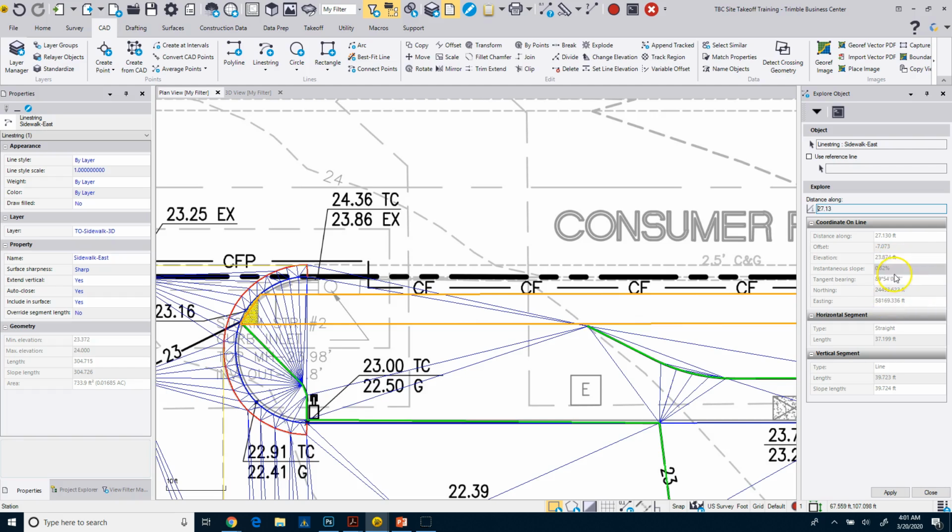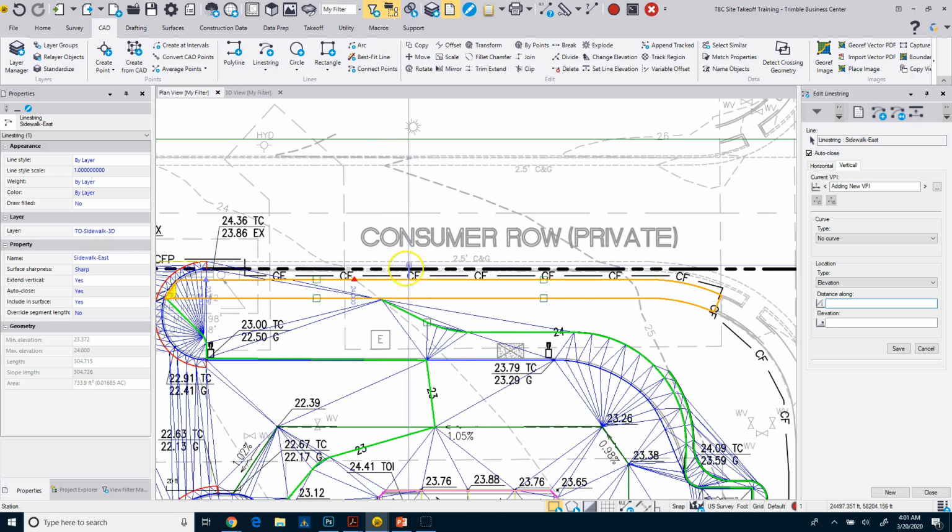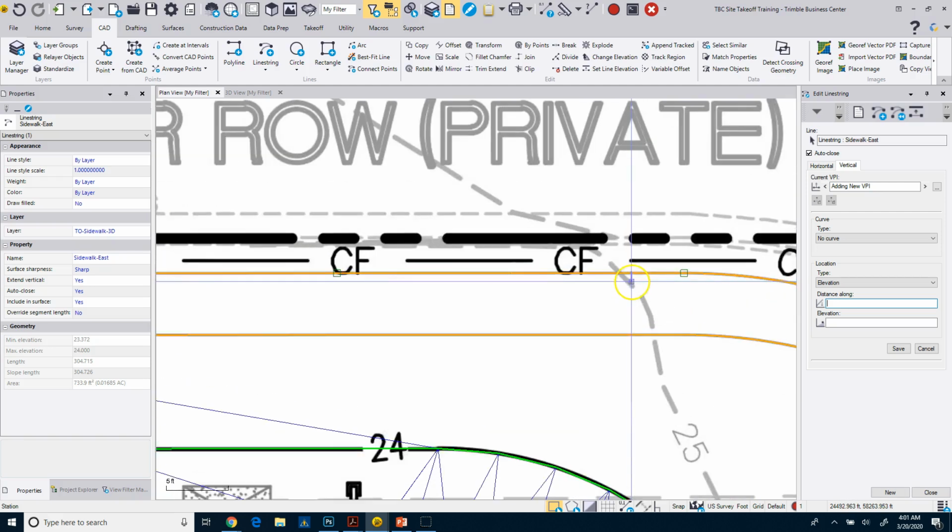That's probably good. I'm better than 0.5% going this way. As I come back around, my cross slope will be 2%, hopefully, and I'll be good, right? Again, splitting hairs maybe, but just trying to be somewhat accurate with my information. So I just want to make sure that I'm not way off, is what I'm trying to accomplish here. So now I can put in another elevation point.